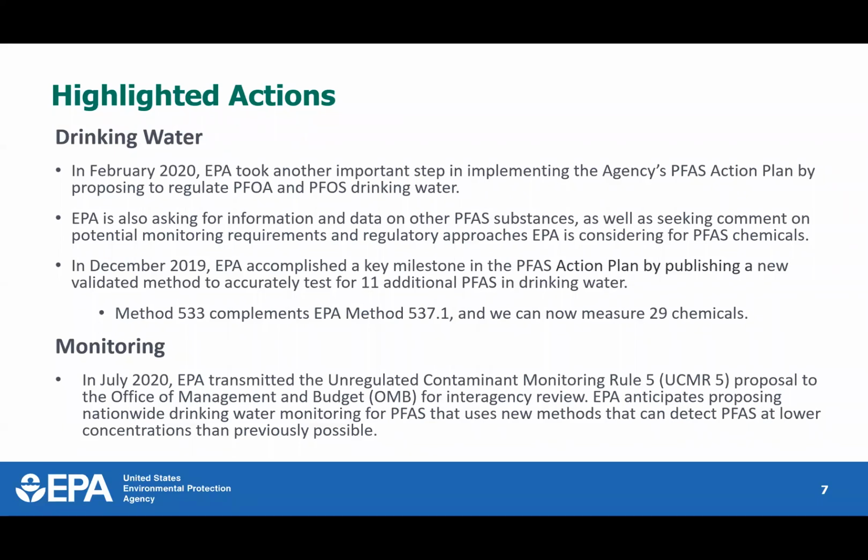I was going to ask, I thought that EPA tested for PFAS in the 2012 or 13 to 15 time frame. But now this updated UCMR, this updated testing, you're using new testing methods? Is that what the difference is? So you're correct. The UCMR 3 in 2017 collected drinking water data for 6 PFAS, which were PFOA, PFOS, PFBS, PFNA, PFHxS, and PFHpA. And so yes, this is expanding it to a list of other PFAS chemicals. Okay, thanks. And go ahead, Joe.